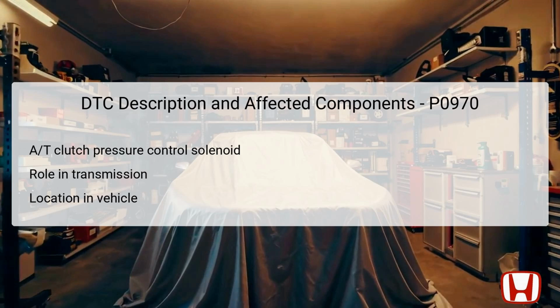Electrical signals from the powertrain control module, PCM, command the solenoid to open or close, ultimately affecting the gearing mechanism. If the solenoid is experiencing an open circuit or short, it can severely limit the vehicle's performance and cause erratic shifting behavior. This is crucial to diagnose accurately since the solenoid's failure or a related electrical problem leads to the DTC being stored in the system.